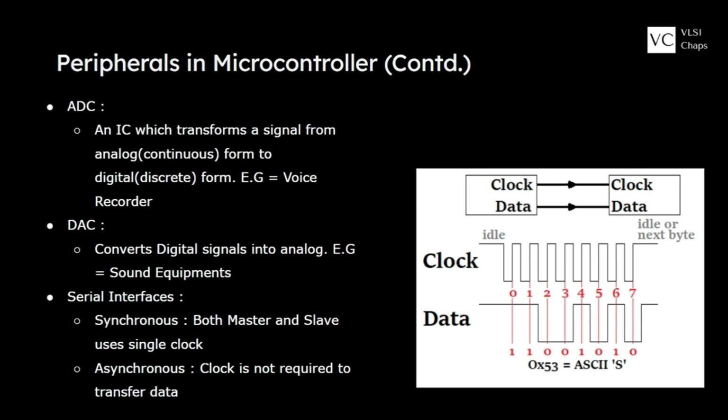At the receiver end, we don't need to add any algorithm or functionality by which the receiver will know that this is the start of the frame and this is the stop of the frame, because each and every bit in that frame will be passed with one single clock pulse. And as the clock pulses are synchronized between transmitter and receiver, they will get the data in a synchronized manner without any loss.